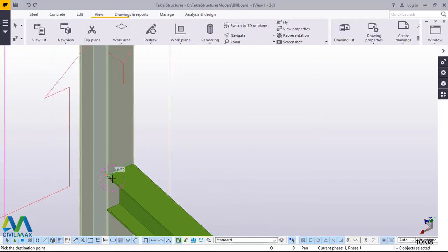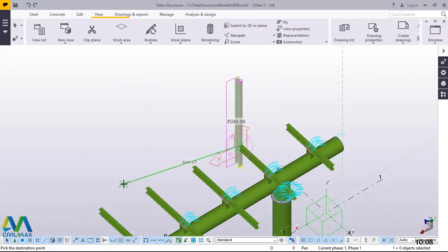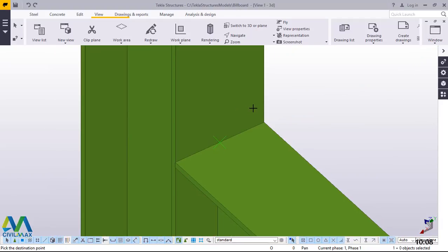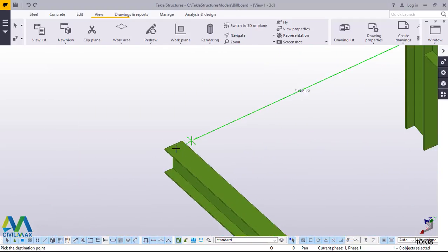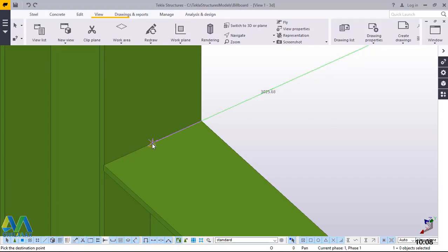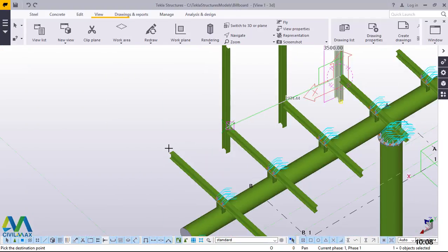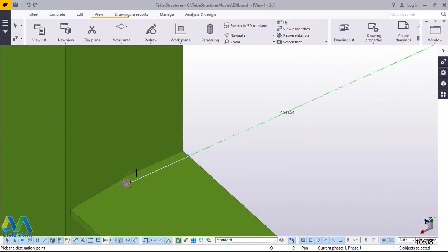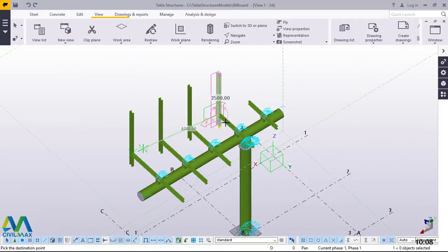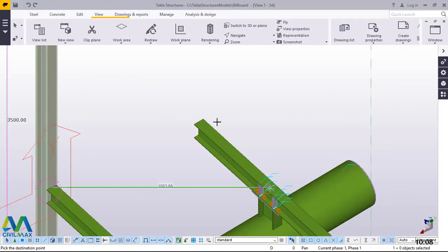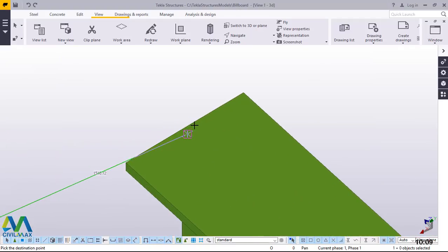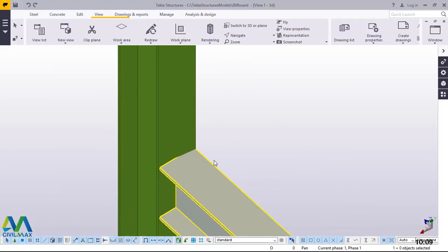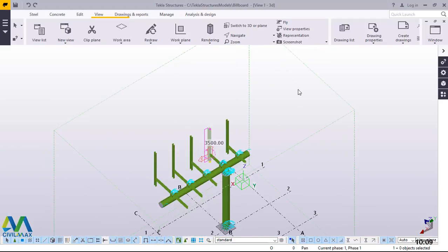Then that is the point we want to pick it from. I'll snap right there, then move to the next member, then snap right here. That is the middle point. Then go all the way and do the same thing right here. There we are, and go to the final and snap right here. Perfect. Now what we're going to do next, we'll just mirror this after copying all those. Let me just snap right there, right click and go to interrupt to exit that command.